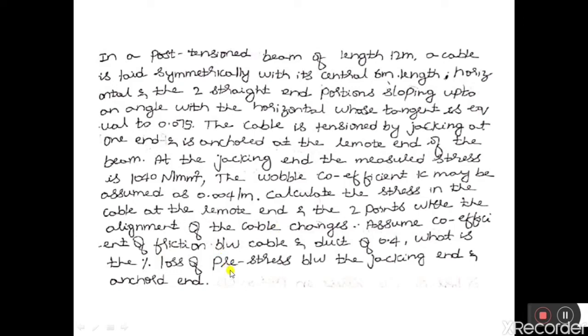0.004 per meter. Calculate the stress in the cable at remote end and the 2 points where the alignment of cable changes. Assume coefficient of friction between cable and duct as 0.4. Then what is the percentage loss of prestress between the jacking end and anchored end?